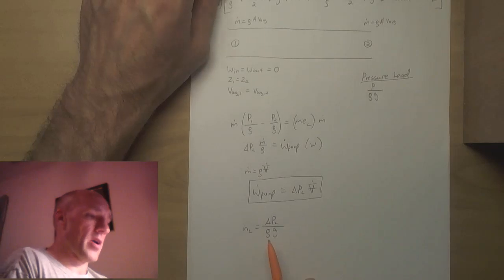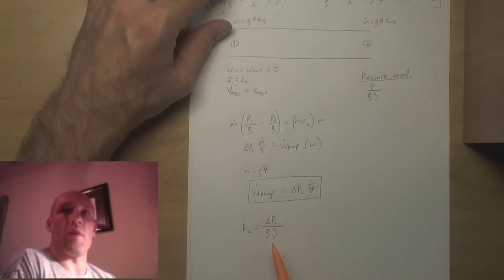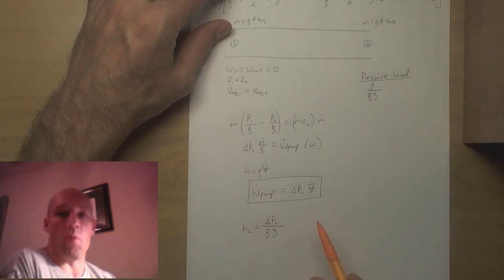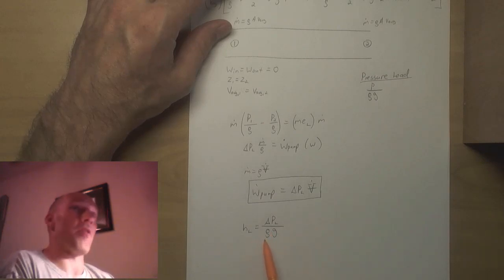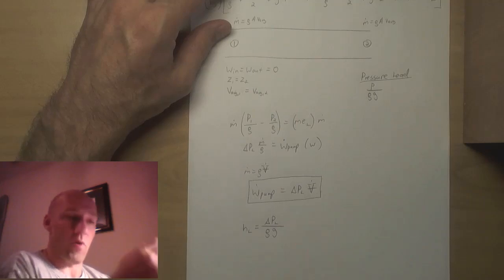I guess mainly because this might have more use in things like pumping water over long distances. How high could you pump the water? You could only pump the water as high as the total head. That's as far up as it'll go and come to a halt.